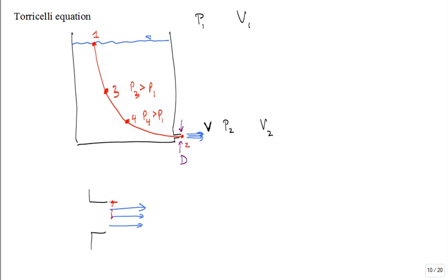Hence, the pressure at the edge is atmospheric. Pressure in the middle is atmospheric. It's atmospheric pressure. So, what about P2 compared to P1? It's going to be the same. Pressure is the same. Velocity is a lot higher. What about the elevation? A lot less. I mean, that's what's making it flow. Z1 is high.